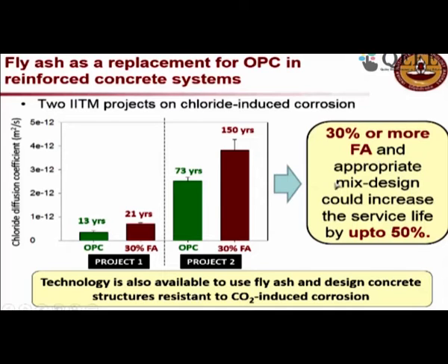This is very crucial. Appropriate mix design is very crucial, and I would even add curing also very crucial, could increase the service life by up to 50%. That means you can have significant increase in the durability if you go for using fly ash, slag, silica fume, metakaolin, all these mineral admixtures or SCMs.